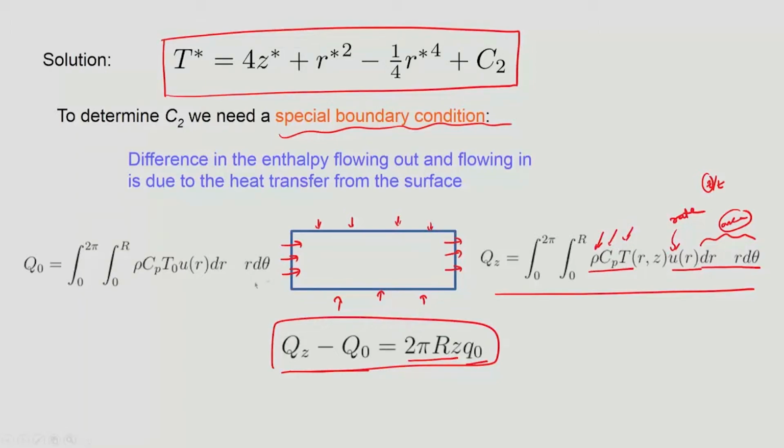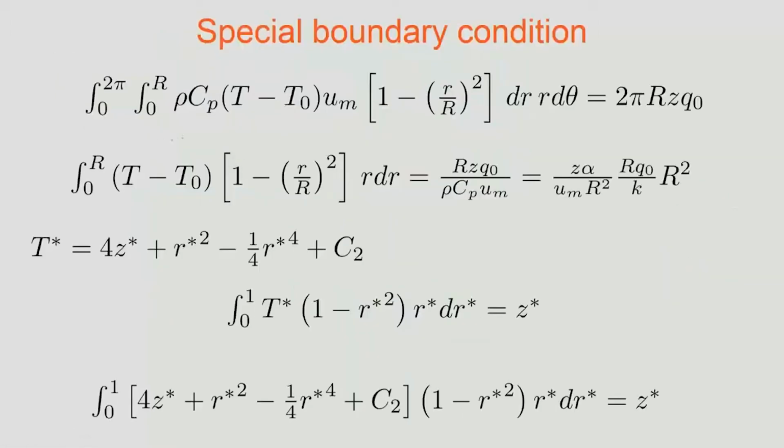Okay. So, similarly what is coming in is written, and then the difference of them is basically T minus T naught into this entire expression, and that basically is written in this form: rho Cp, T minus T naught, into the velocity into the area element, integrated over the entire circumferential area, is going to give you the total amount of heat that has come in. Okay. And this is basically the boundary condition that we want to use, and luckily for us we have already non-dimensionalized T minus T naught. So, we have those expressions that are coming quite nicely.